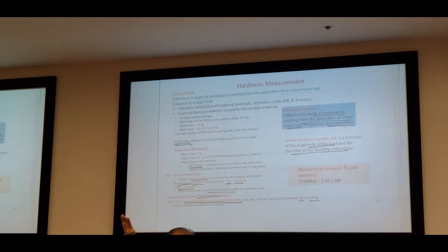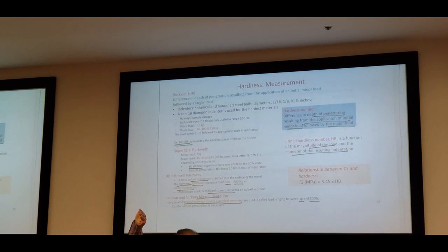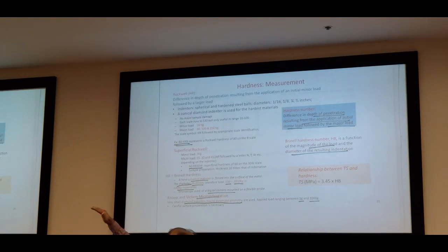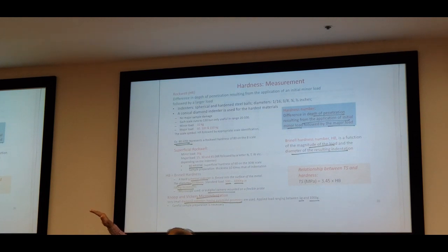You apply a force, applied force versus the strain, the change in force. Stress versus strain. And you have that curve. At some point, plastic deformation starts. And if you still apply, what happens? It reaches a maximum point, and that maximum on that stress strain curve is the tensile strength.